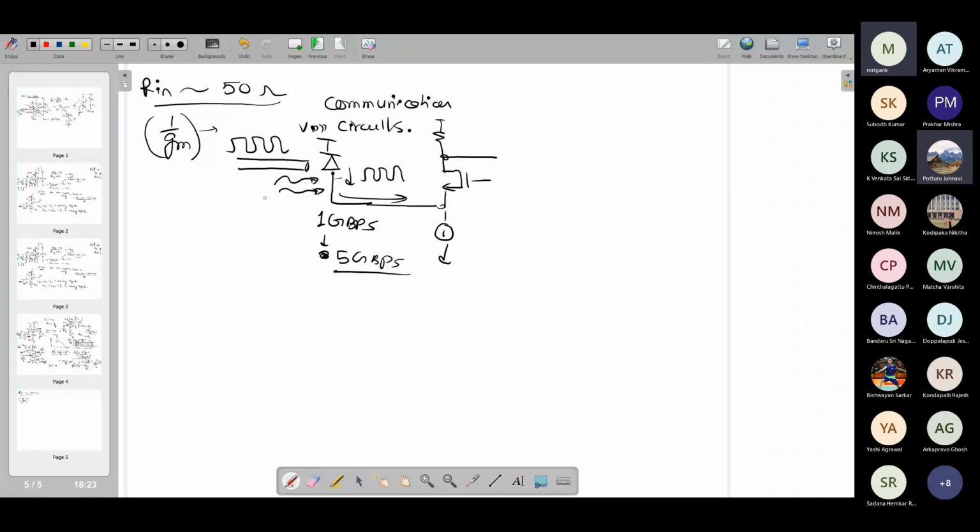That is one example. In this case, the overall current in the diode can be relatively large, maybe 0.1 milliampere all the way to 1 milliampere, and it can be a few milliamperes to start with. Suppose it is 2 milliampere. In that case, even a 500 ohm resistor over here will give you a full 1 volt peak to peak swing, which is good enough. So the gain requirement, the RD requirement, may not be very high.